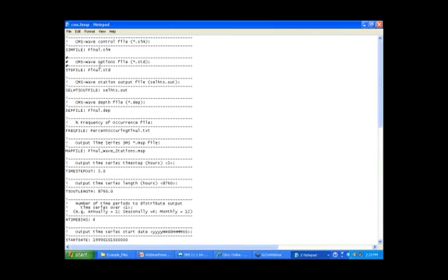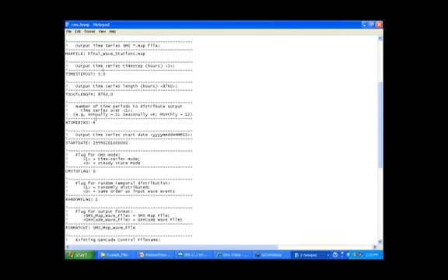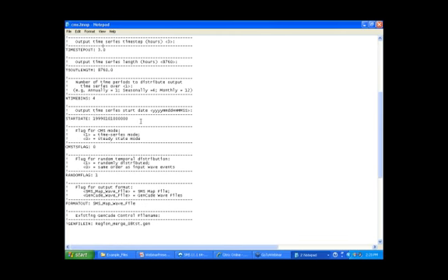So you have the final.sim, final.std, our cell.out, which is the output of the CMS wave observation stations, final.depth, the frequency occurrence file, and this is our output file, so that will eventually be our wave stations, our time step, our time series length, our number of time bins, the time series date.